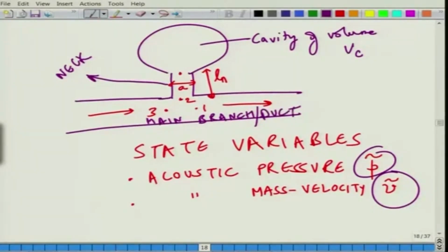The idea is by effectively manipulating or controlling the different physical parameters, dimensions like the radius or the length of the neck or the throat, and the volume of the cavity, which could be any irregular cavity. Spherical cavities, almost spherical cavities are used, or some other box kind of structure or something which would radiate less noise, and we keep adjusting the volumes and all those things in such a manner that some particular tones are eliminated. And when you use a certain combination or array of such resonators, we can control not just one but a large number of tones, because tones can occur at a range of different frequencies.